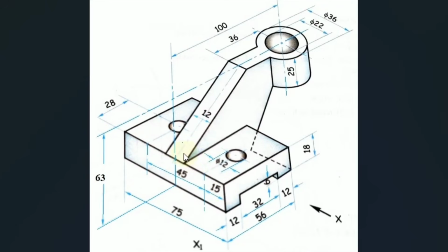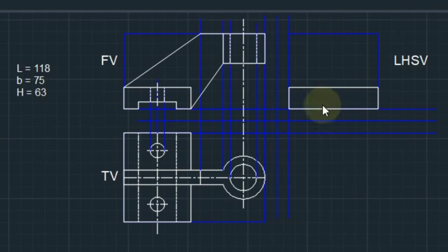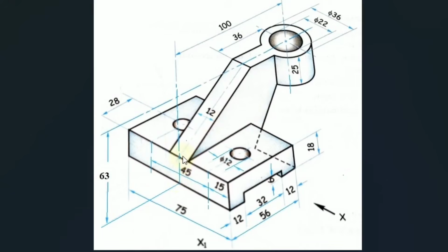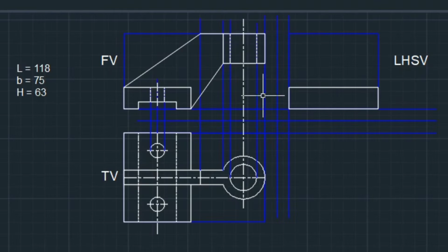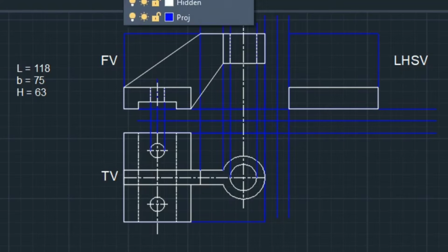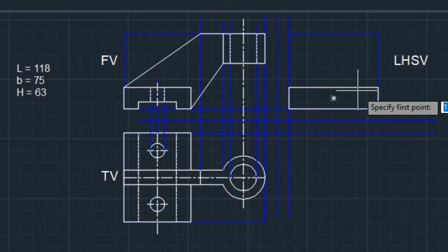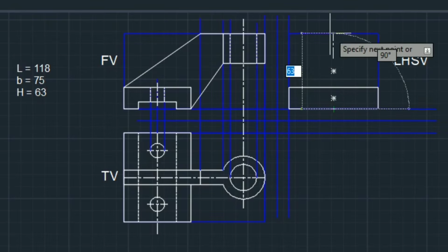Now you can directly draw the vertical plate of 12 mm thickness, which is ending on what? At the top plane. For that we are supposed to draw this axis of symmetry, which will start from the midpoint itself. So take the line command using the center layer, and join mid to midpoint.